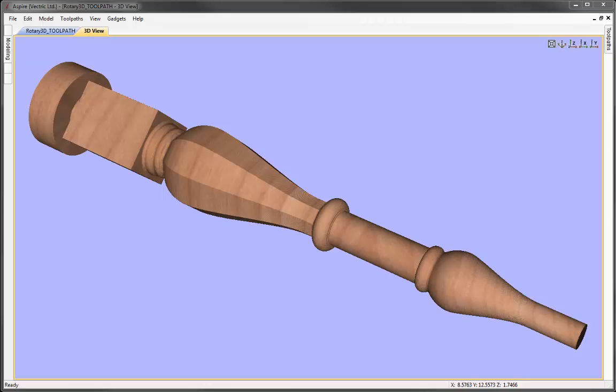In this video, we're going to run through the process to create the model and toolpaths that would allow you to cut the part you can see on the screen here with a rotary axis set up on a CNC. I'm going to start by doing the standard wrap job setup so that we can orient and size the part correctly. Then we're going to import a simple set of vectors, do a swept shape and show you how to create toolpaths on that version of the object.